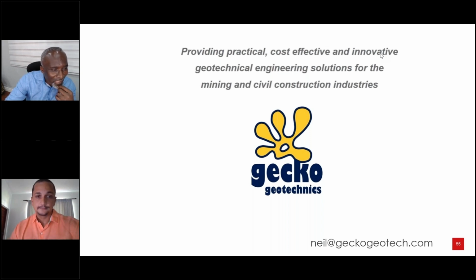Thanks a lot. Now somebody is asking whether Slide 2, we know, can do transient analysis. Now they want to find out whether Slide 3 can. So the first thing I'll say is Slide 3 does not do finite element analysis. You will have to do the finite element groundwater analysis in RS3 and import the results into Slide 3. Now RS3, similar to RS2, can do steady state and transient. So the answer is yes, we can do it with the Rocscience suite, but for 3D, you can't just use Slide 3. You would have to use RS3, as things stand now.